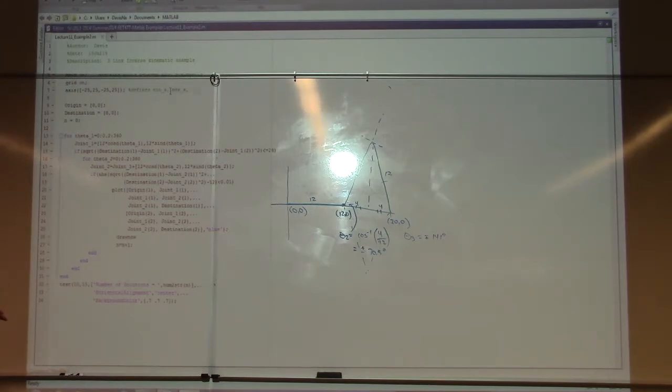If the shaft is coupled to a larger diameter pulley, then it would be increasing the resolution by decreasing the step angle. If you go from a larger diameter to a smaller diameter, so if you have a larger pulley on the stepper itself, coupled to a smaller pulley, then you're going to be decreasing the resolution by increasing the angle that you're stepping through.